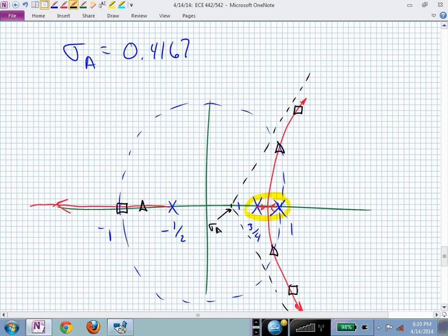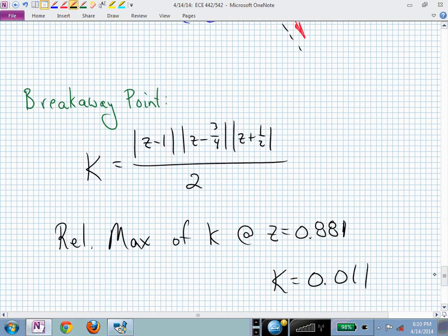And you could say, oh, maybe that's the value of z where I just escaped the unit circle. And even though it may not be on the root locus, you could plug that value in here for k just to get a feel for how big k is close to that boundary. You're trying to get an intuitive feel for the gain for stability.